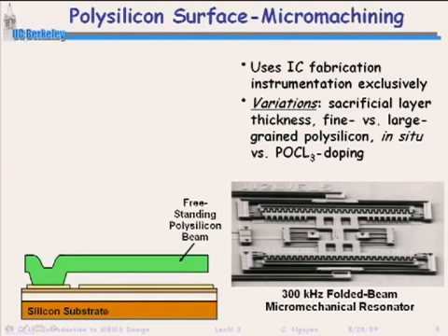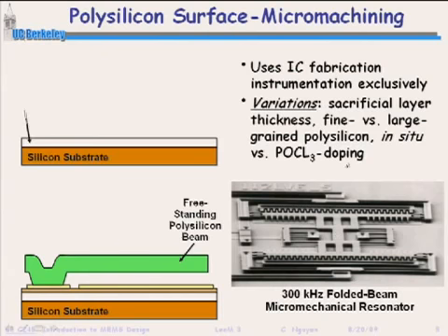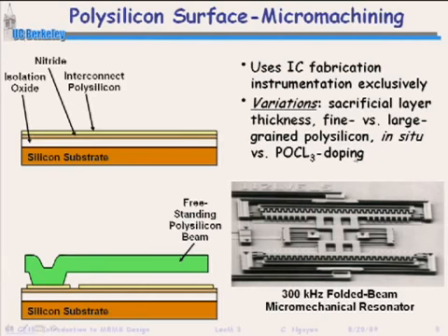The way you do this is, start with your substrate, and you notice we're just putting films down. Okay, films right there, and then we etch the film. So we're etching. Put another film down on this, etch this film. Another film on this, etch that film. Then finally etch out this layer that's temporarily supporting that film there to make a free structure like that.